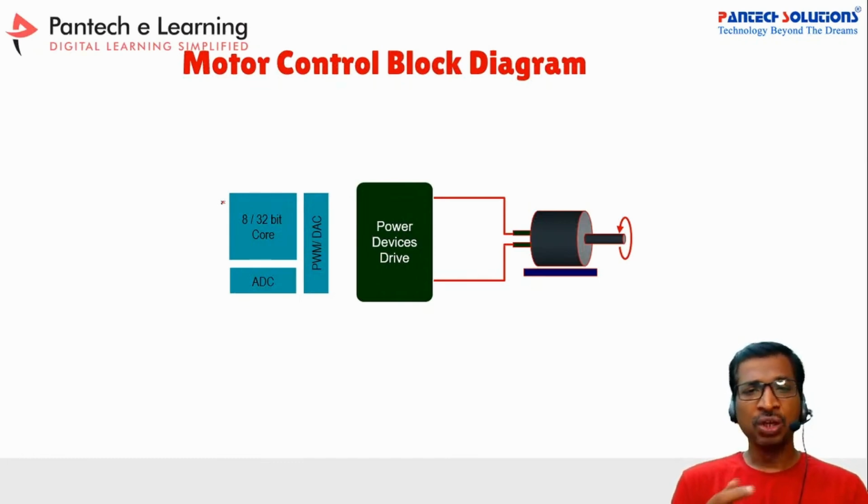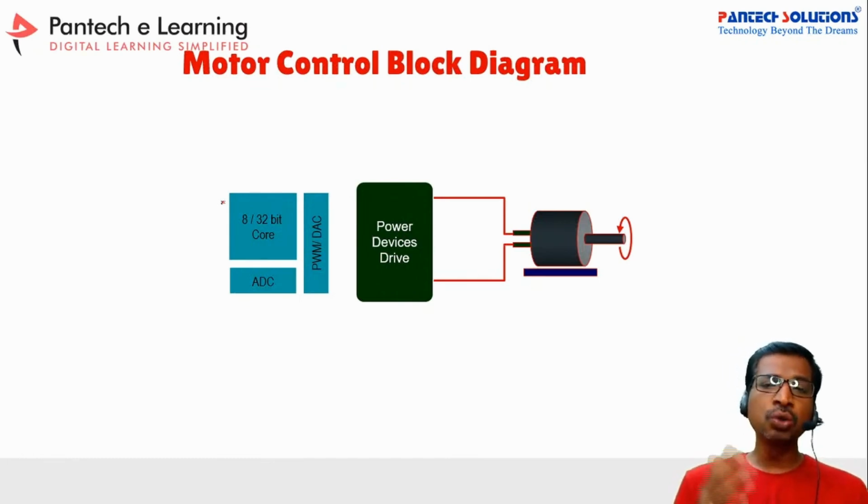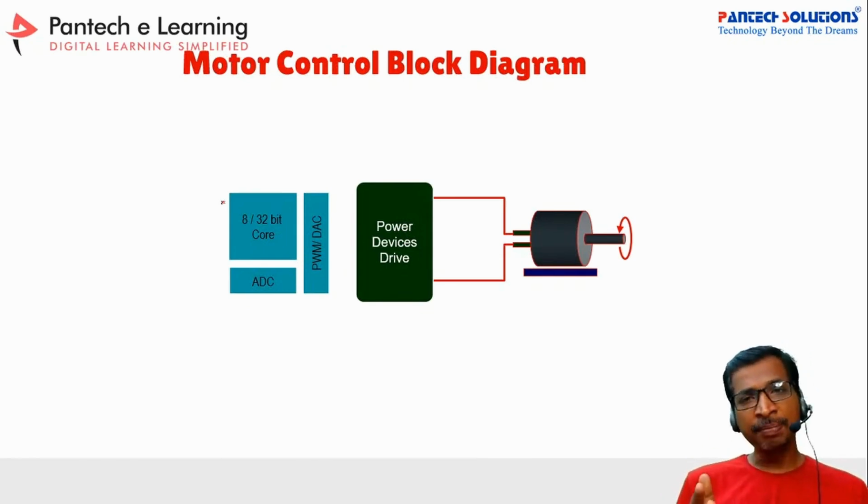If you want to run the motor in closed loop application, then you have to choose higher order, high power microcontrollers like a 32-bit or 16-bit microcontroller. In that, like Microchip based DSPs or ARM processors or Texas Instruments based DSPs or FPGA processors. These processors are going to give you closed loop control mechanisms.